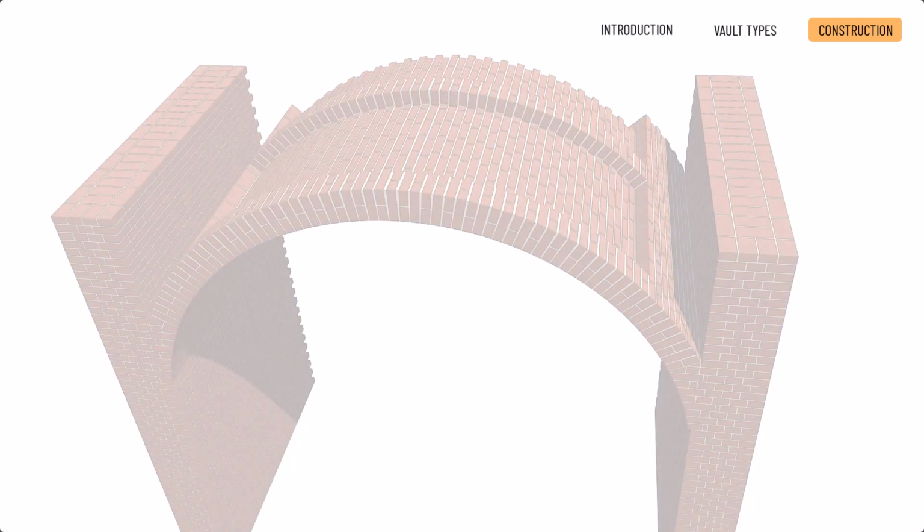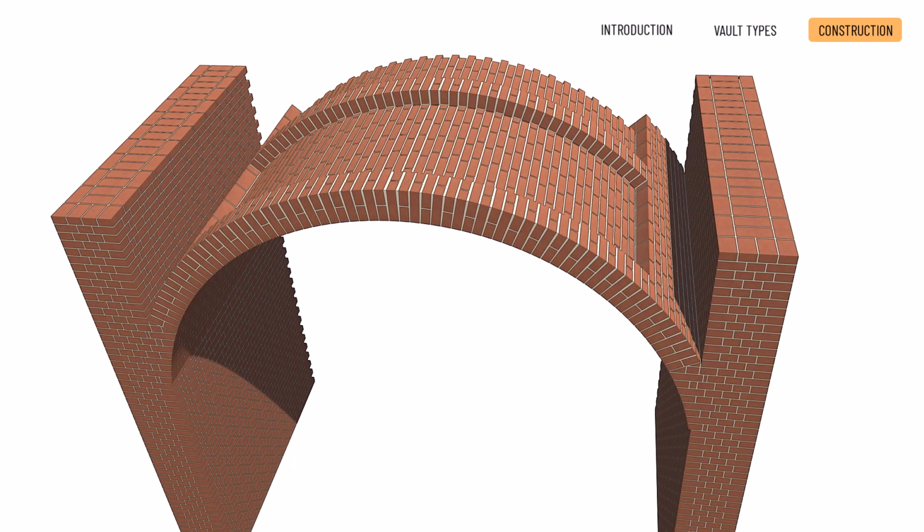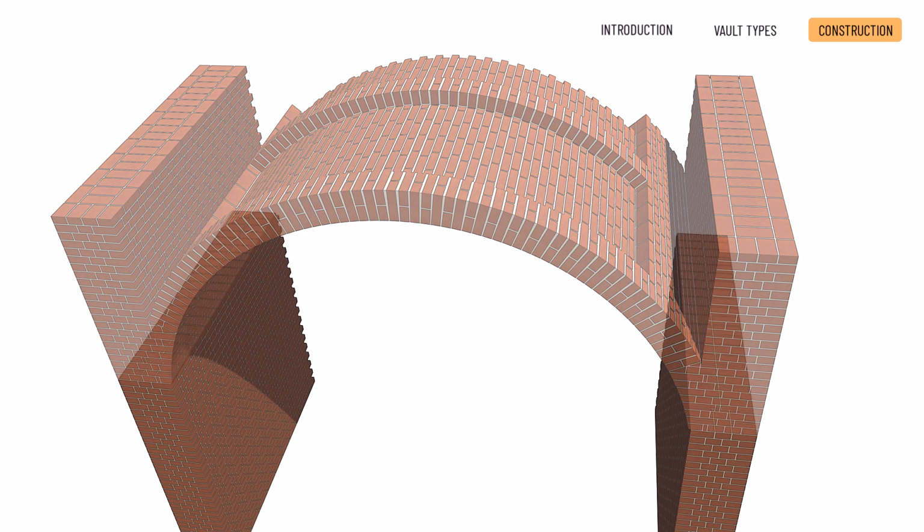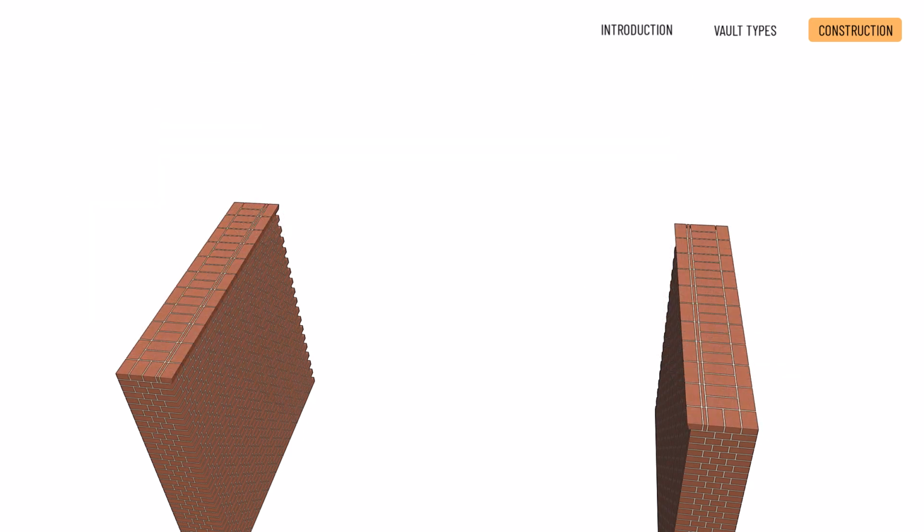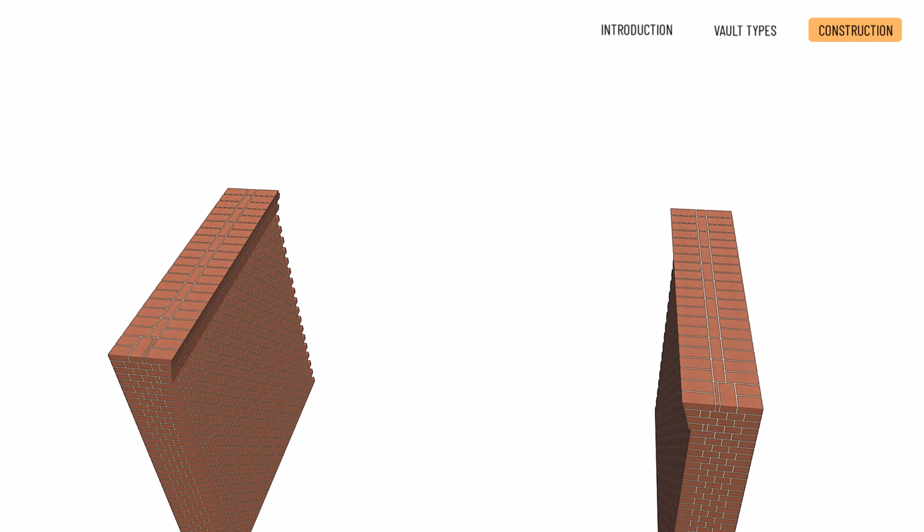Construction of a vault. The vaults were built as a continuation of the walls using the rules of good bonding. Due to the geometry of the arched structure, the radial elements create wedge-shaped mortar joints. For arches with a greater radius of curvature, it may be necessary to carve the bricks into a wedge shape. We will demonstrate the process and concepts of the simplest type of vault, the barrel vault, using brick as a building material. 1. Starting from the baseline, starting line, you mason the impost where the vault should begin.